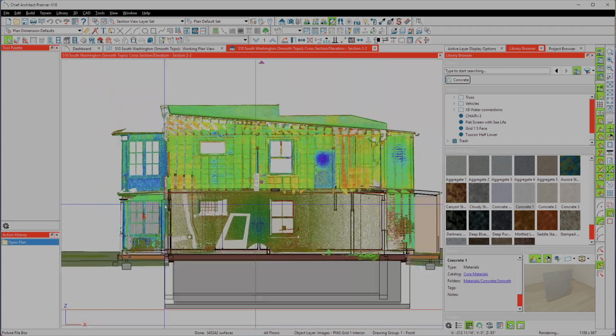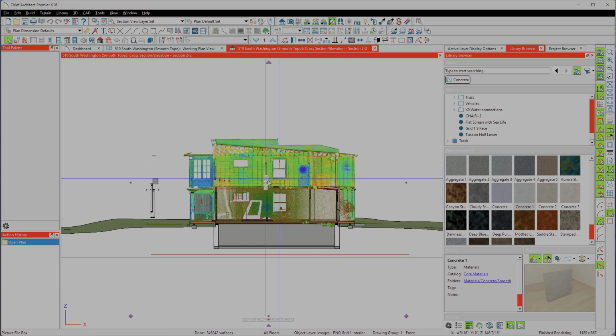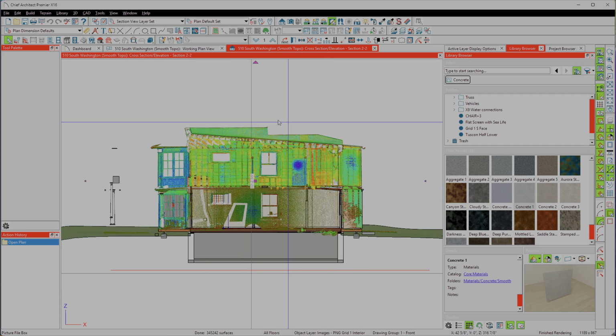It's just gone because there's no transparency, and it's too strong of an image, especially when I'm using this setting called intensity, because I'm getting this image out of Autodesk ReCap Pro, and it's a LiDAR scan of the existing building, and then I can bring that in.